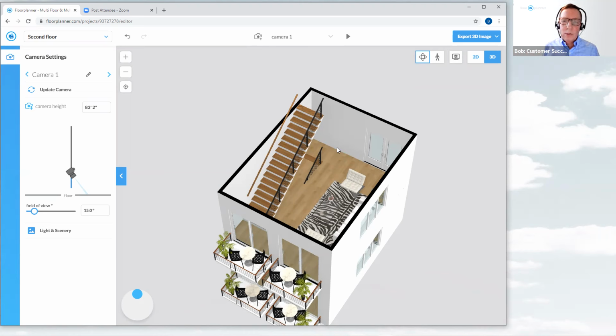So be cautious of changing any heights. Make sure that all of your walls are truly at the same height, because some people I've seen have had difficulties with multi-story projects where there's some separation between the floors. Floorplanner will try to read a wall and its height and make adjustments accordingly. This worked great because everything was clear. Those balconies are nothing but balconies attached. There are no strange wall heights out there.